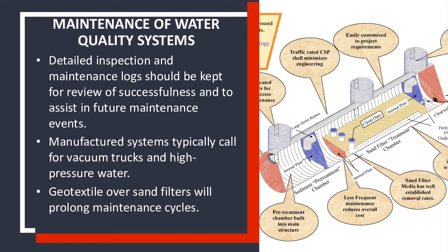These call for a vacuum truck. They also call for high pressure water. But a lot of times what you can do is put a geotextile over your filter media, and that will help prolong the life of these systems, because that can be removed, which removes your bigger debris and your bigger sediments.